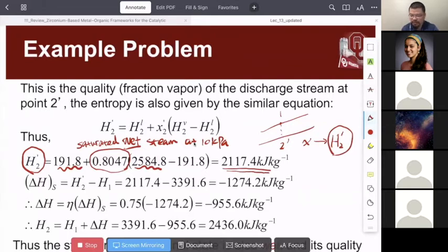And you can see that we are following this isentropic process. So the enthalpy difference between the two states shall be the isentropic, or the maximum enthalpy change we could have for those two conditions. Okay, so we have H2 prime minus H1, which is exactly from the steam table reading, and we know this is the delta HS over there.